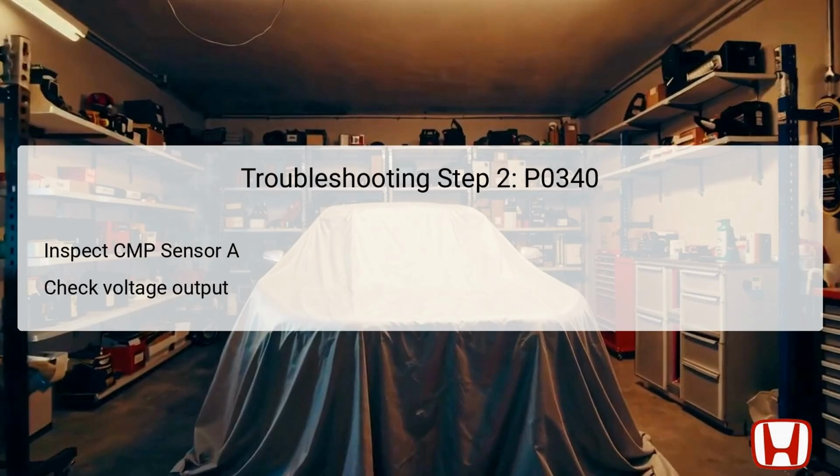In the second step of diagnosing the P0340, you must focus on inspecting the CMP sensor A directly. Begin by disconnecting the CMP sensor A 3P connector. This is crucial, as it allows for a clear inspection of the component without interference from the PCM. At this point, using a multimeter, check the voltage output while the ignition is on.